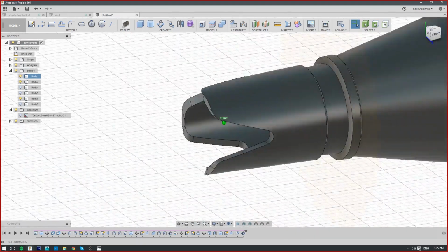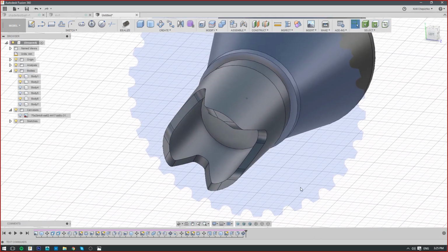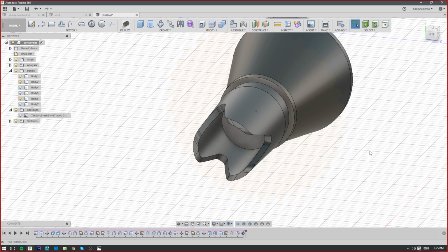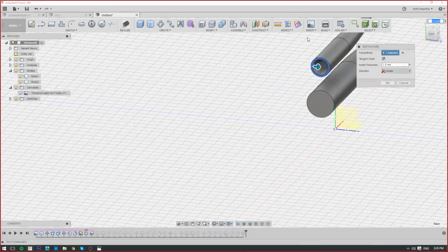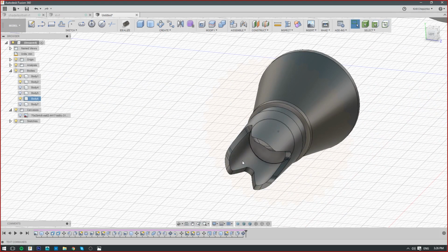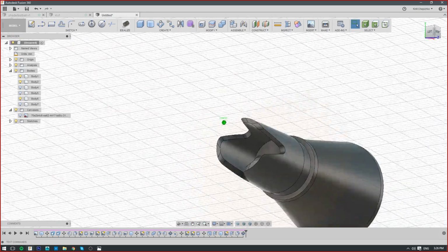It's so useful. If you set things up well, then later on in your design you can still make some changes with the timeline. Exactly. It has its own repercussions. I like to say the butterfly effect. If you're trying to change something here, it's just gonna roll the marker all the way down, and it may influence whatever you've done here. Like if I go back and delete this original cylinder, everything down the line will be broken, and you won't be able to fix that.